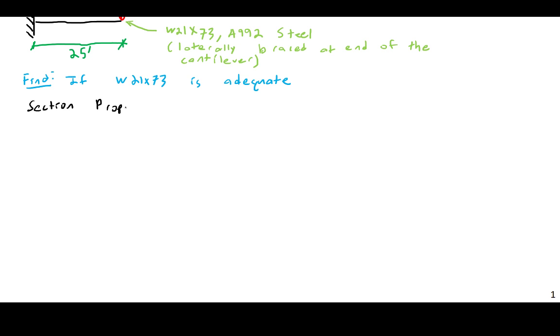Alright, so I'm just going to be doing a lot of writing. Well, let's see. We have the A, the D, the area, the cross-sectional area, the beam depth d, the thickness of the web tw, the width of the flange bf, the thickness of the flange tf, and that's it for this column. The area is 21.5 inches squared. The depth of the beam is 21.2 inches.